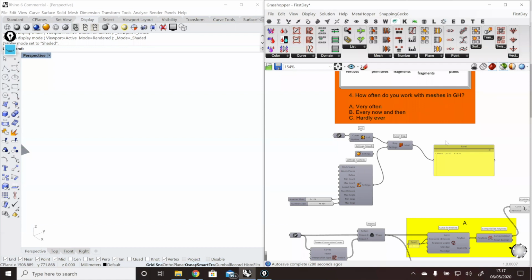Then if you can't really control that, for example, there's a link question: one of my definitions needs to import a mesh from a 3D scan. If you do have to process the mesh inside Grasshopper, that's always going to be computationally intensive, because reprocessing and reducing meshes is very computationally intense. So the advice is, as much as possible, this operation should be done as a pre-processing operation before it's used in ShapeDiver, in Grasshopper, because Grasshopper is not really meant as a tool to reprocess your meshes in the first place.